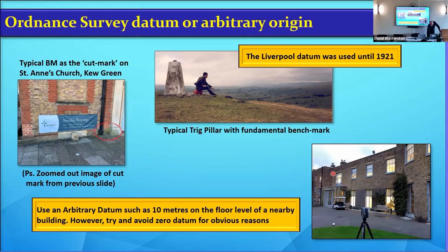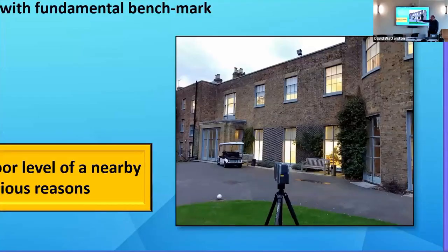And that is a little image of my laser. That's the scanner set up. Let's zoom in on that. So that's the scanner set up. That's me. The points that I observe to find out the position of that. And I've 4 or 5 or half a dozen of them set up everywhere. At every setup, I observe them before I move it, and it finds out where it all is and knits it all together.